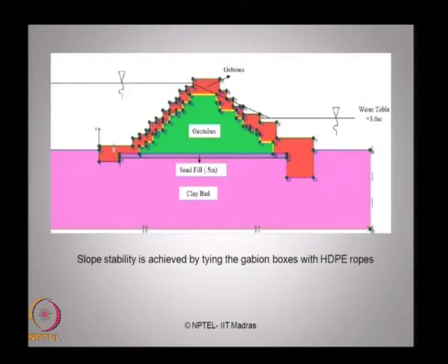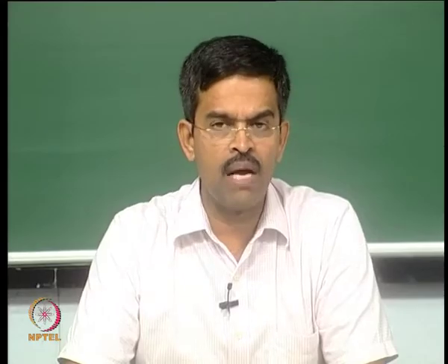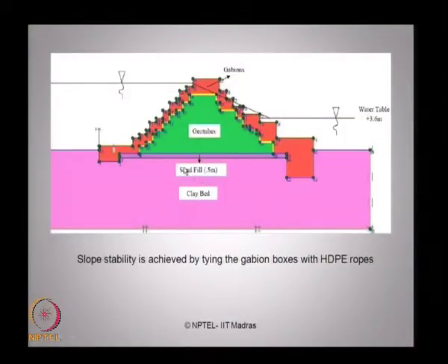Now, as there is no permanent rigidity offered by this kind of arrangement in the whole embankment, we can see that the integral component of the geotube with that of a gabion box maintains a high degree of flexibility in the heave direction as well as in the direction of wind action or wave action.